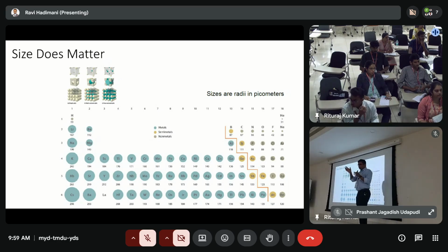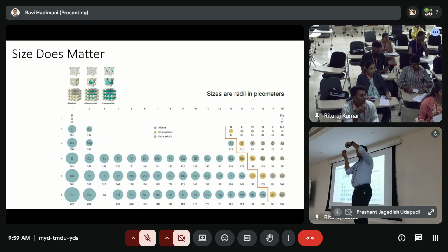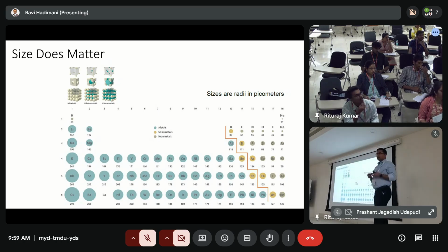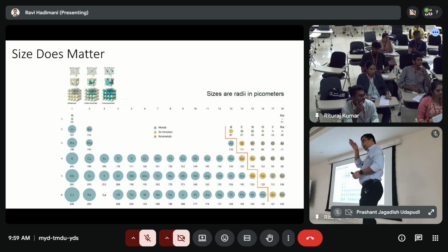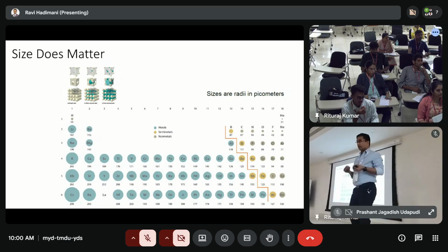Usually, if there is a van der Waals force, the center of each atom tries to align, right? But if one is really big and one is small, and then you have more atoms, what you are really doing is creating some residual stresses between the top layer and the substrate. If they have similar atomic radii, then there won't be internal stresses in the thin film.